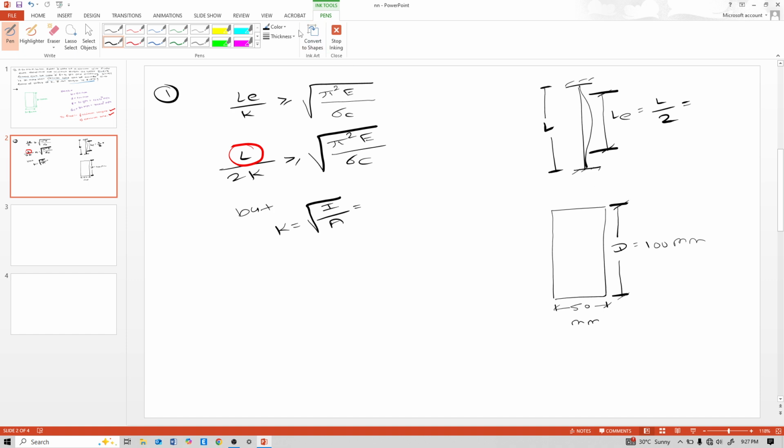So, calculate the moment of inertia, and remember that this is a rectangle shape. We are always interested in using the least moment of inertia in the calculation. So always remember that for the least moment of inertia, the axis passes through the minimum length of the rectangle. The minimum length is 50 mm, so pass that axis through like that. Consider this as the y axis.